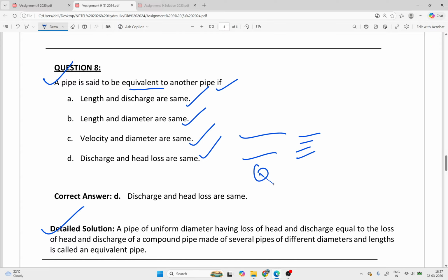So what you will do is, discharge is equal to n times the small d discharge, but the condition here is that the length of all the small pipes should be the same, and the diameter of all the pipes should also be equal, then you can write this relation. Otherwise we have to go with the concept of parallel pipes and series pipes.